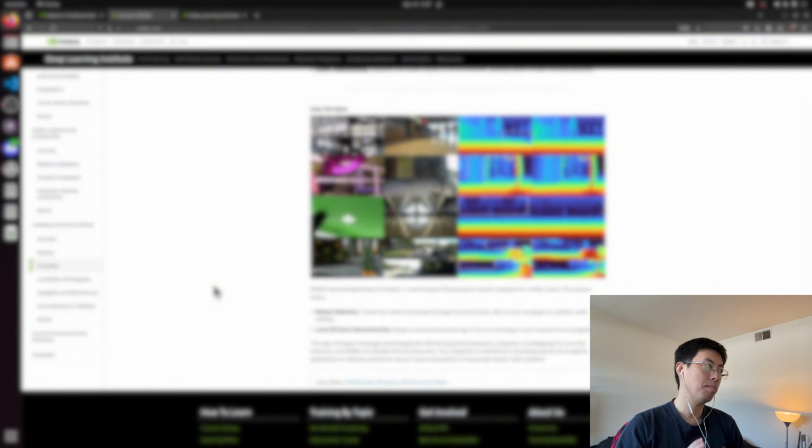Something that might not be well known to the public is that you can do something called visual odometry. Visual odometry takes a sequence of images and tries to estimate how the camera is moving. A good application is that you can use a camera alone, or maybe combined with an IMU, to do indoor tracking, where you don't get a GPS signal. You can use a camera and go around, and it will know that you turned left here, you walked through the hallway. That's visual odometry. Very powerful stuff in autonomous vehicles or mobile robots.